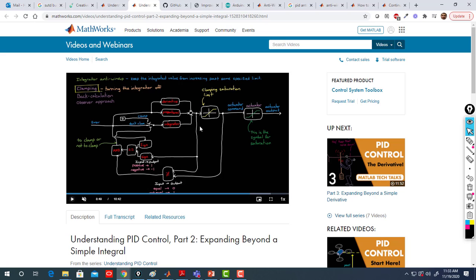You need to check the sign between the output of your PID block and the input of your PID block. Take the sum and check whether they are the same or different. Then, according to that, you have a logic gate that switches your clamp to 0, meaning the integrator is taken out, or switches the clamp on or off.